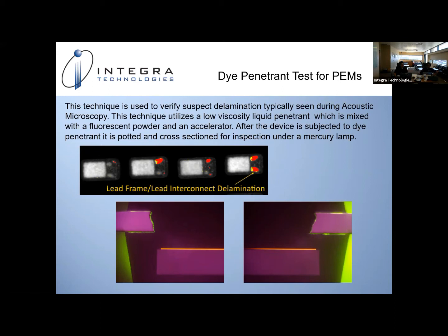So if you have a hermetic package, no, CSAM will not work. If you have a ceramic stacked capacitor, it can work, but it may not get to the depth you need it to. And it's the physics of acoustic microscopy.